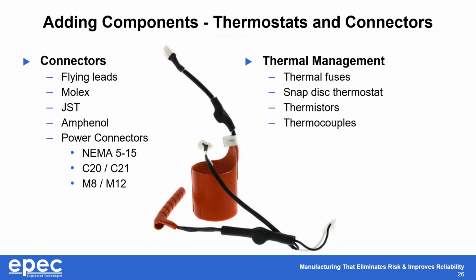While most of our customers do need flying leads or just cut ends, a lot of our customers do need us to crimp the terminals on and stuff the terminals inside a connector for whatever the application is. Other customers who have UL requirements may need us to put on a NEMA 5-15 type of connector or other power connector that has a UL mark on it, all of which are things that we can support.